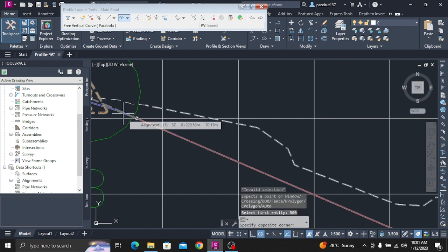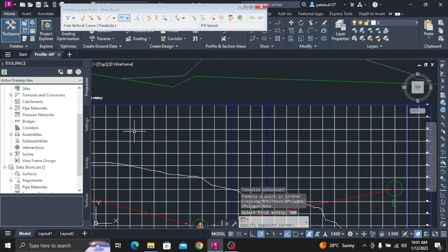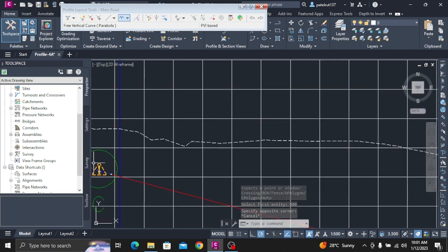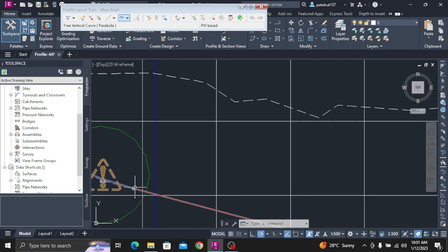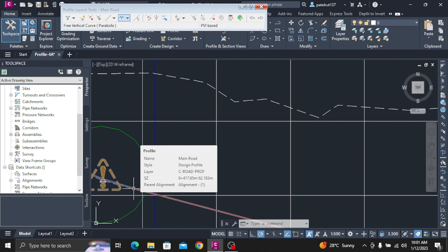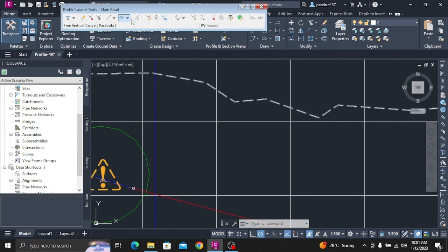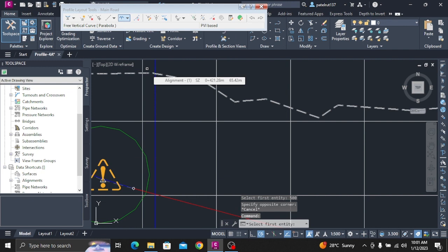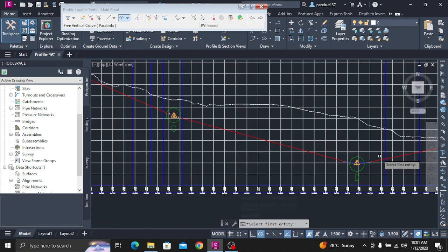Click Next. On the Profile Display Options page, in the Select Stacked view to specify options for list, select Middle view. Note: the number of views that is visible in this list depends on the value you specified for number of stacked views in Step 5. In the Specify Profile Display Options table, select the Draw checkbox for the following profiles, e.g. Centerline. Centerline. In the Select Stacked view to specify options for list, select Top view.